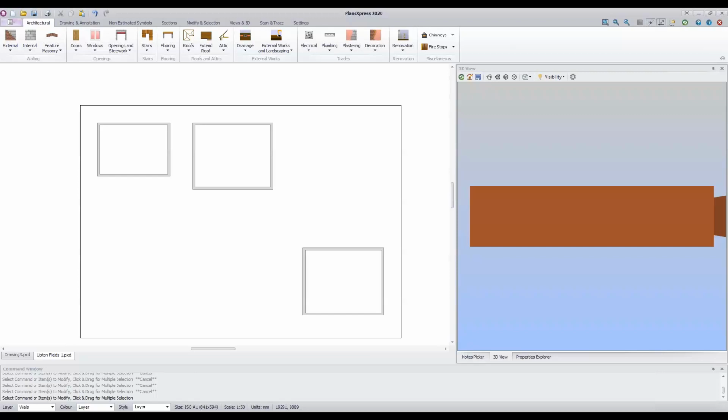Okay, and there's one more really important shortcut key that I would like to introduce you to at this point, and that is the R key. Now the R key allows you to place a new item on screen relative to an existing point. So for example, say this is a house I've drawn here. Maybe I want to draw the garage, and I'm going to draw it relative to the corner of the back of the house. So to do that, I can use the R key.